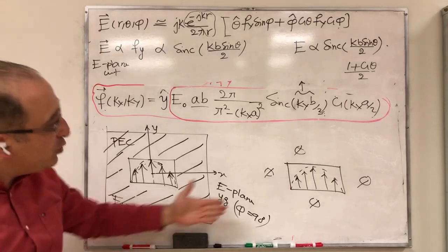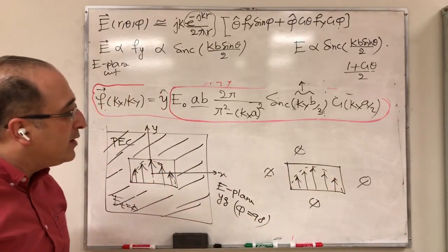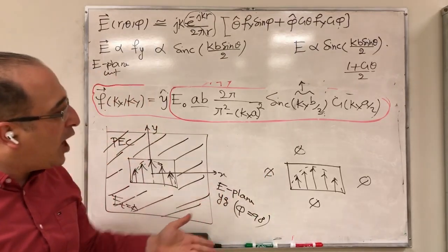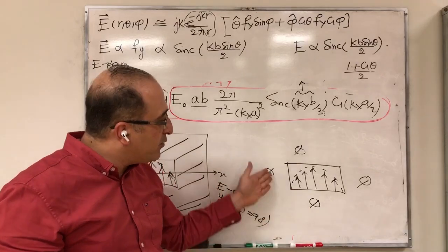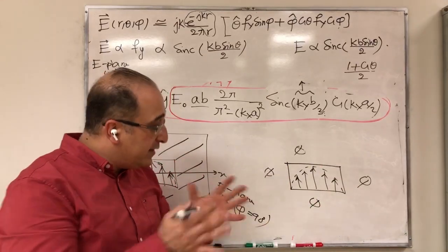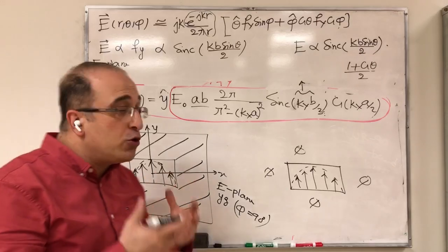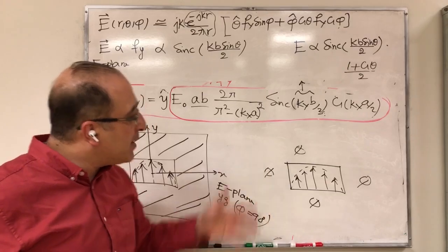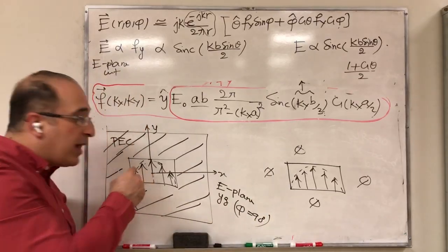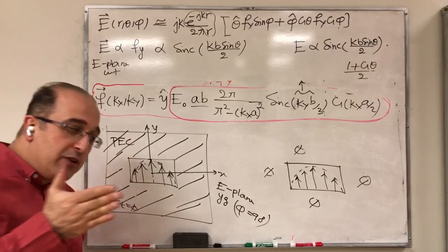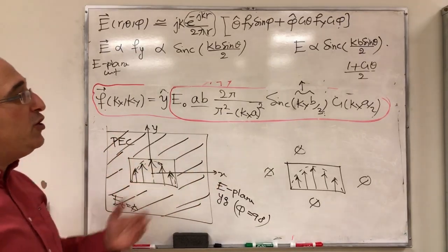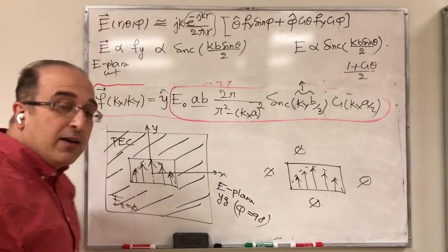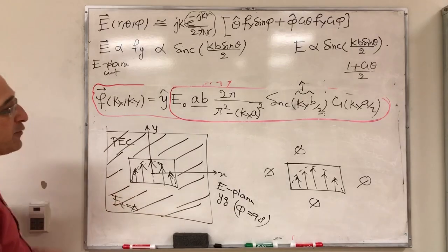So if I give you an open-ended waveguide antenna and I accept from you that you assume outside is 0 in this course, you should also know that this approach involves an approximation, and this approximation is more accurate when you are on the main beam. When you are diverging from the main beam, you get more of the effect of this term here. So that's one thing to keep in mind, and this was for the E-plane.